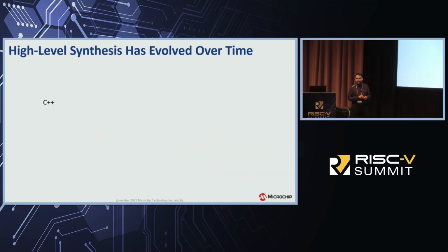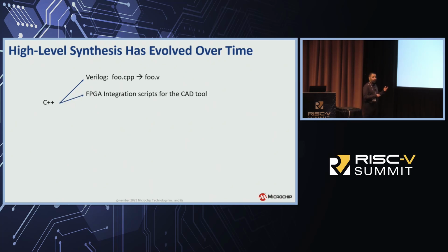So if you're not familiar with what high-level synthesis is, it's a concept that has been out there for quite some time now, but it's basically taking a function written in C++ and the compiler can generate Verilog for you. But it has been evolving over time, and now modern HLS tools also generate integration scripts. So not just generate your accelerator, but also integrate it automatically into the system. A lot of things can go wrong during integration.